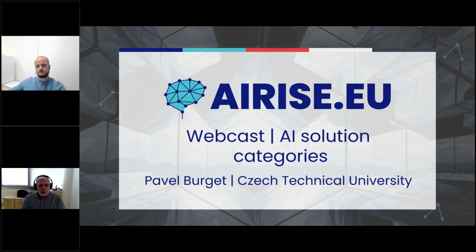During the training process, which is supervised, the classification is done so that there must be some human intervention that says which data are OK, which data are non-OK, or represent OK or non-OK parts. And then during evaluation, when the AI solution runs on real process data, the existing data are assigned to the classes, and in this way the SVM evaluates the parts accordingly.